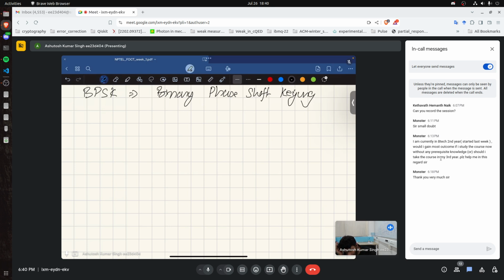You remember the electric field I had written as E naught e raised to j(omega t minus kz plus phi). In the last case, OOK, I was varying the amplitude, whereas in this case I am varying this phi.